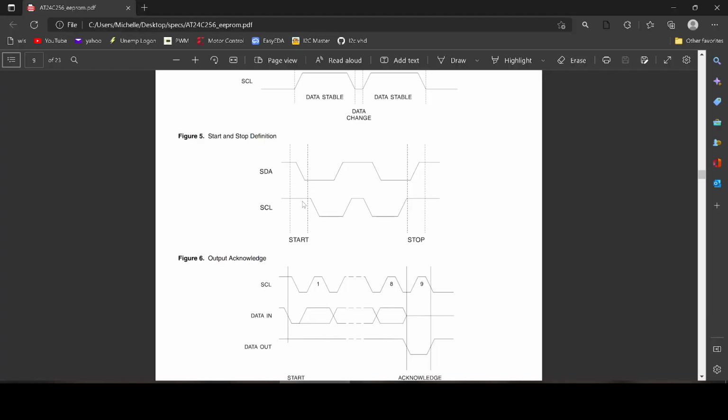And then we would send over our data. Like I said, there are 4 pieces of data that go over: the slave address, the high part of the address that you're writing to, the low part of the address you're writing to, and then the actual data. So those 4 bytes, and for each one of those 4 bytes, you send over the data you need, and then you get an acknowledgement. Whenever the serial clock is high, you get your acknowledgement from your slave.